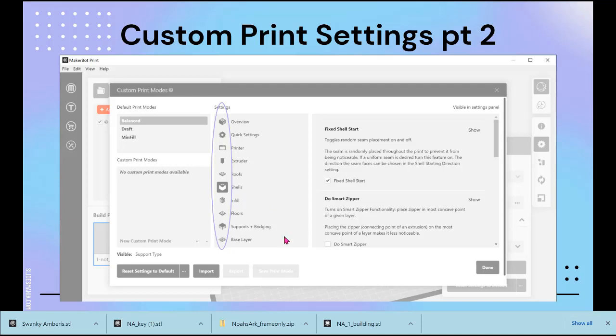The other thing that you are likely to change in here might be your base layer. So if you are making something like those key guards, those are really flat and thin, and they're large and thin. And so usually by default, what the printer is going to put down first is what's called a raft as a base layer.